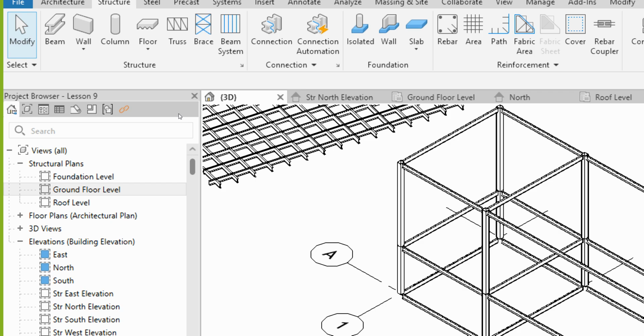The same thing. Okay. The same concept. So every building component you are creating, normally when we are doing construction, we do it floor by floor. Any construction that you do, first you do the foundation first. When you finish, you do the filling before you cast the ground floor slab. Then you erect, if there are columns, you erect the ground floor columns.